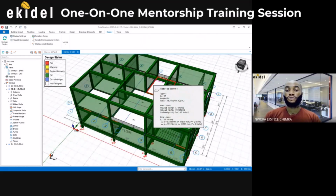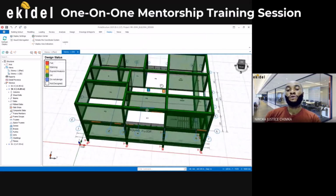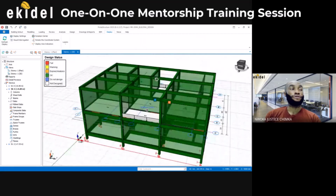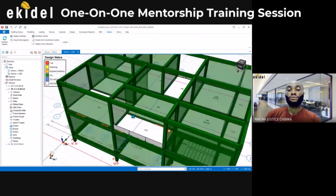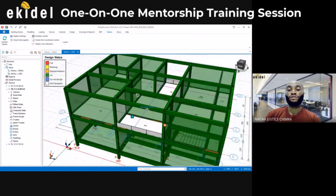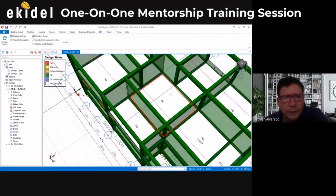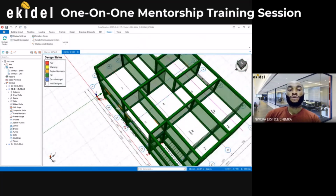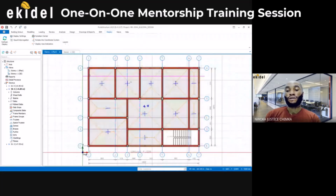Okay. So today's training will be on the slab design and then the pile foundation. Once you're done with your building design and everything, you can see that your slab is still showing white, which means not designed. So we now have to come back to our plan view here and then design the slab. And how do we do that?